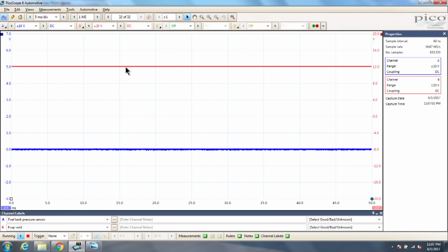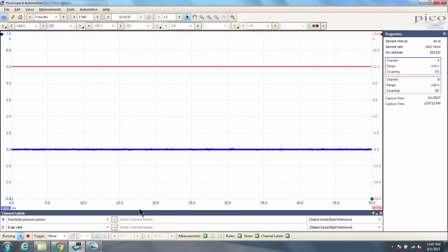Okay, I'm going to leave this thing sitting out. Keys off, right? Keys off, PCM power relay is out. And our vent solenoid right now, pin 20 of the PCM, and I'm 100% certain this is pin 20, green and blue, I believe that is. Yep, green and blue. Pin 20 at the PCM has 12 volts currently.